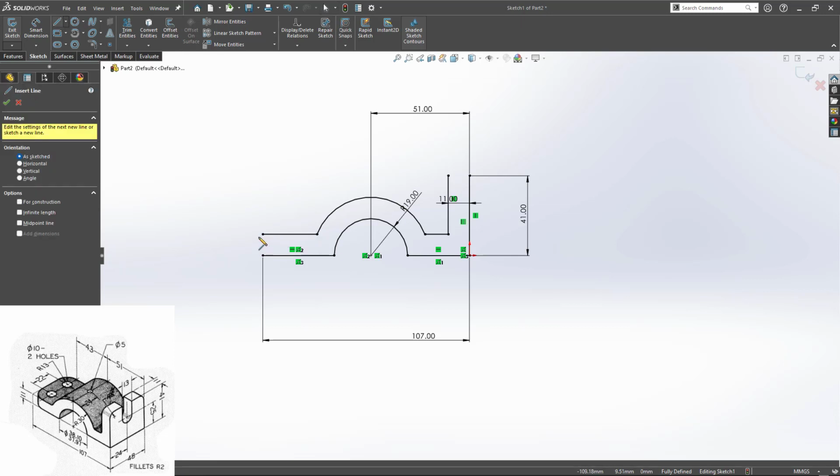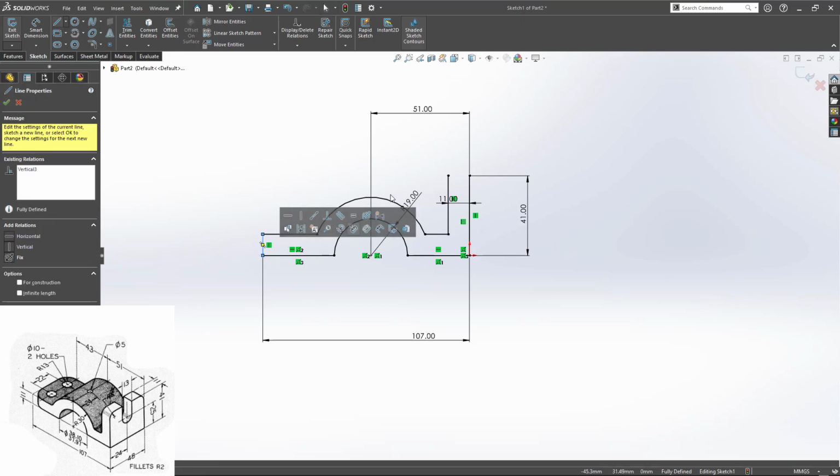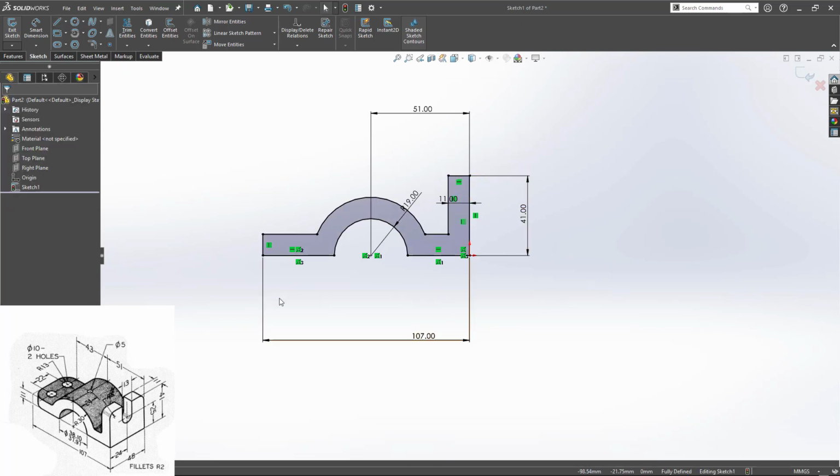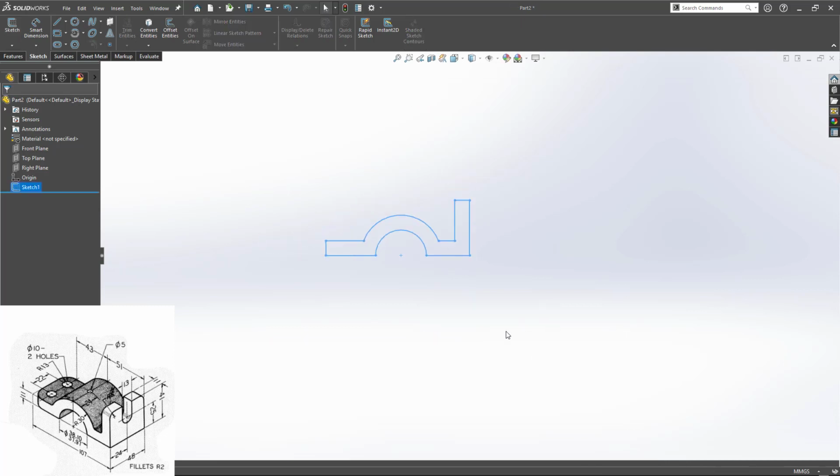Now just close the sketch using the line tool. This is done. You can see this is the closed profile now. It has the color indication. You can turn it off, or shade it with the contours if you want. I'd like to keep it because it will help me recognize whether the sketch is closed or not. The sketch is fully defined. I'd like to exit the workbench. For inserting and exiting, the shortcut is the same, Q. You can even set it up.